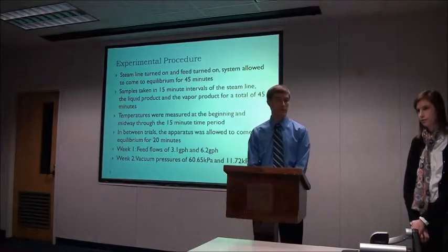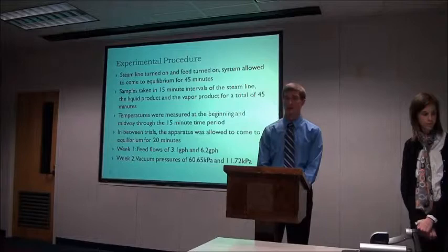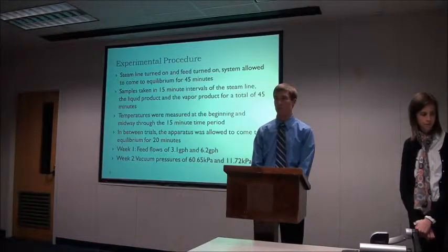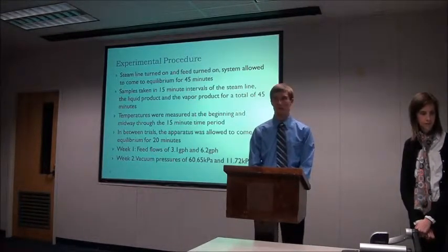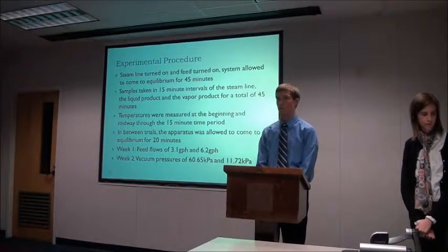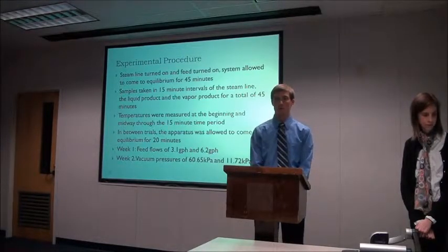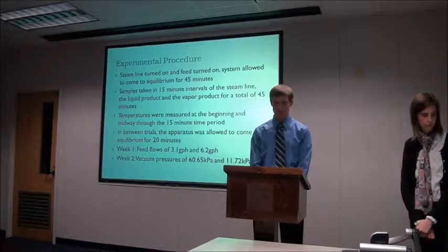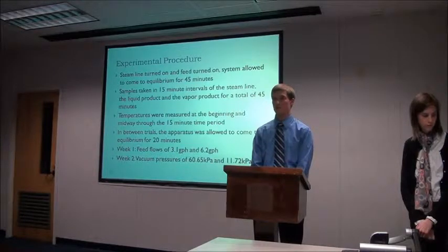And we would collect this steam and the liquid for 45-minute periods, collecting it whenever it filled up all the way. We would measure it at 15-minute intervals, but we would also measure the temperature and the pressure of the steam every 7.5 minutes to 15 minutes, depending on what the system was.